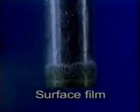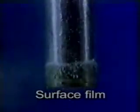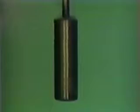These examples illustrate one of the most important principles in quenching. Quenching is a surface phenomenon. Cooling is controlled by the viscosity of the fluid and the thickness of the fluid film at the cooling metal surface. Less viscous fluids like water cool faster than more viscous fluids like oil. The layer thickness of a quenchant surrounding the metal, in the case of a polymer, will also affect cooling rates. Higher polymer concentrations will increase the thickness of the insulating polymer film, which will further reduce cooling rates. Therefore, anything that affects the formation and breakage, thickness, and uniformity of the quenchant at the cooling metal surface will affect the overall cooling process.